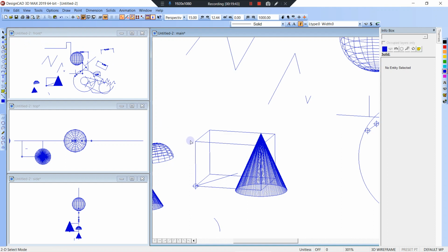We could just type A, right, for arc, and then it's going to be 50 degrees. We could hit that over there. F3. No, arc 50 degrees. Get rid of the H and snap to that surface down there.